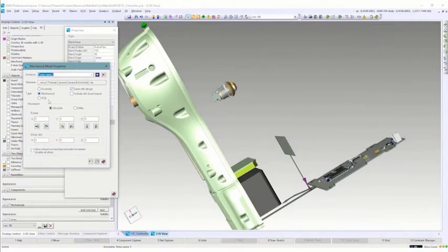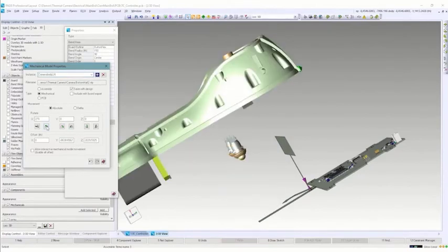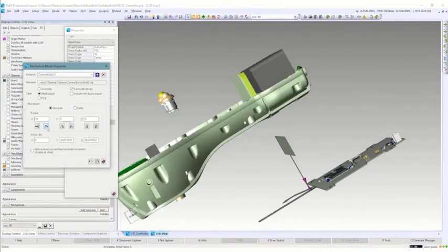It's a mechanical model. As you can see, we can bring in PCB models as well. So if I'm doing multiple PCB models or stacking of boards, I can bring in multiple PCBs and stack them. Or if I'm just interconnecting between two PCBs, I could use a PCB model to determine where it mounts and how to connect it with a flex or other connectors for that matter. So let's call this camera body lower half. Now I need to rotate this around to get it into the right position. Oops, that was right where I wanted it, right there.